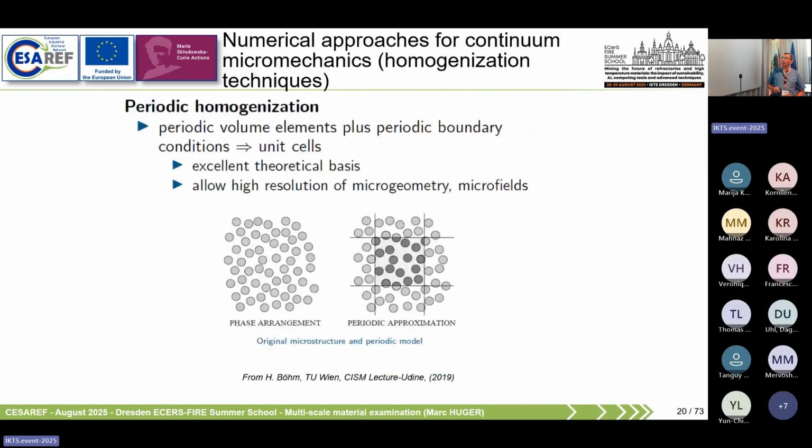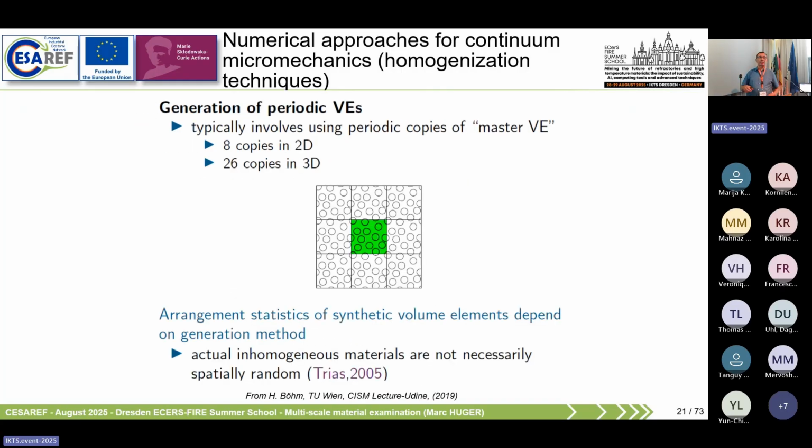From that, we can also consider, of course, more recently, a lot of numerical calculation using finite element modeling. More recently, we have done a lot of things using discrete element modeling. I will not present anything about discrete element modeling, but if you participate in the ECerS Congress, you can see a paper from Harry about that. But the key point here, if you do numerical modeling to describe microstructures, is to consider the right boundary condition. Typically using periodic boundary conditions in order to mimic the large structure of the material in good conditions.